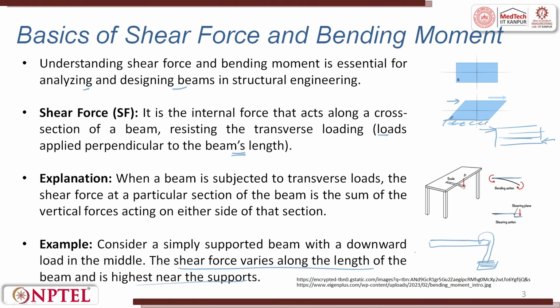This is very important. When you have a simply supported beam with a downward load at the middle, the shear force varies along the length, this is along the length L of the beam, and it is highest near the supports.